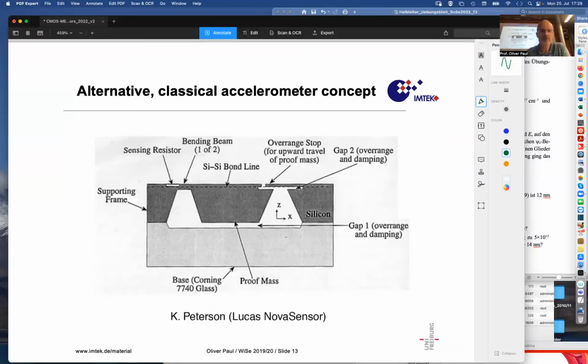Those were built from some anodic bonded glass silicon compound with a mass, and had nothing to do with these complicated etching technologies that we just talked about, these high-performance accelerometers that are now modern. This used to be a simple seismic mass, M, suspended by some bending beam with some bending stiffness, and integrated in it were some sensing resistors.